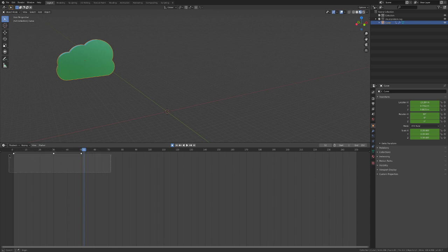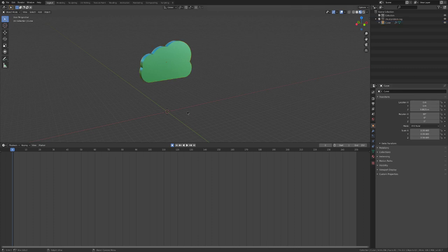So what I'm trying to say is that you really know before you start what is going to be your animation like. If you're animating the rotation, you want always to start inserting a keyframe in the rotation. If you know that the object is just gonna move, well, just don't care about the rotation, don't add the keyframe in the rotation, because it's gonna just add more data to your scene and it's gonna be useless.